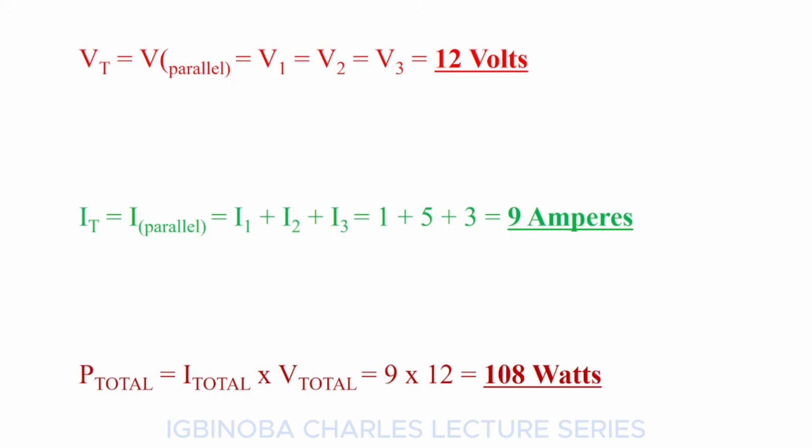A panel's short circuit current depends on a number of factors. One of them includes the area of the solar panel, the irradiance, and also the temperature. But a panel's short circuit current can be as much as 10% higher than the panel's nominal current rating.